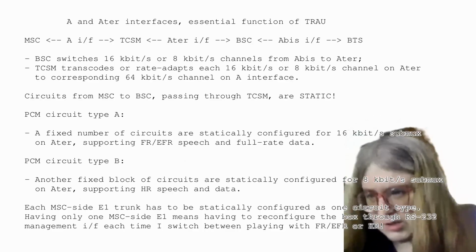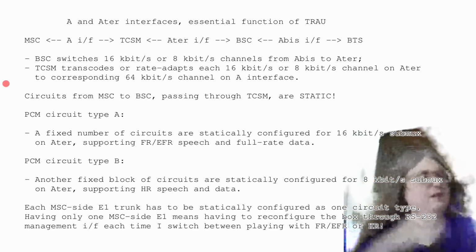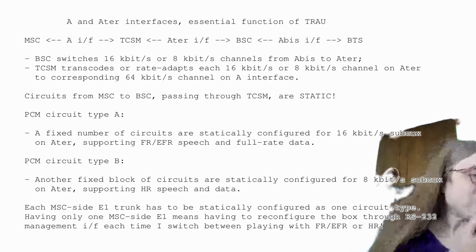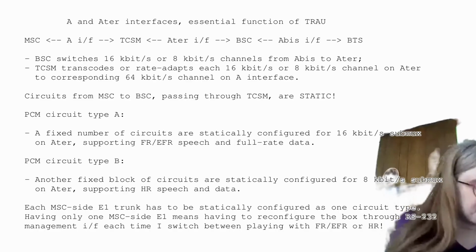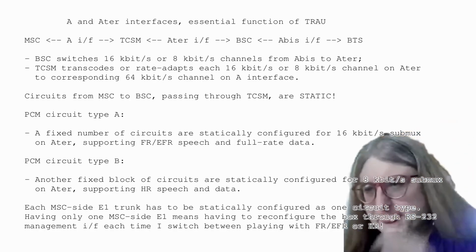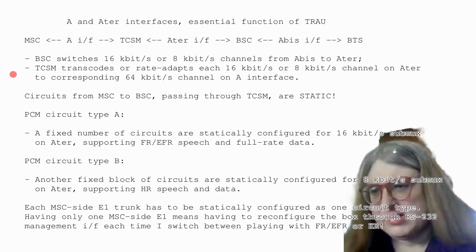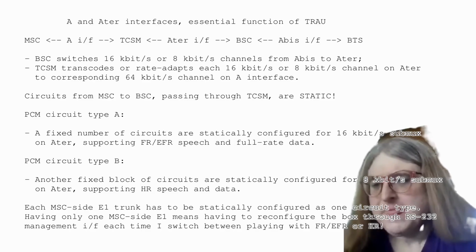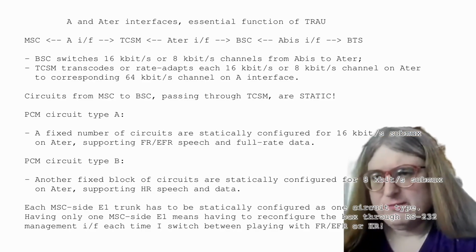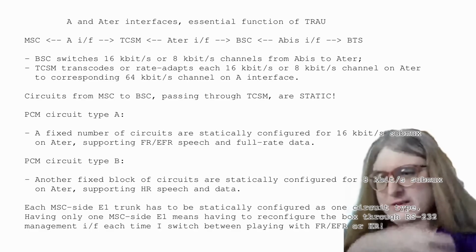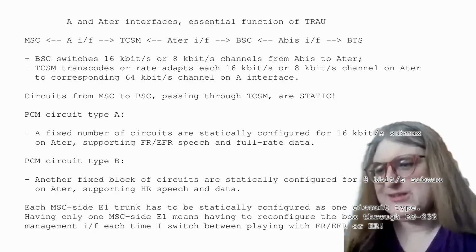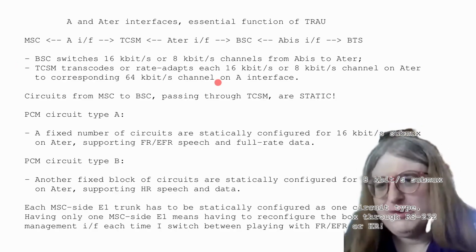And so here we can see, we're kind of moving from the hardware to how it operates. As we get onto the operational side, a quick review of how E1 BTSs work. So you activate a traffic channel on the BTS, and the BSC does multiple things. First, the BSC is going to tell the BTS, please do a channel activate on this timeslot, and the BTS will start putting out TRAU frames on Abis.